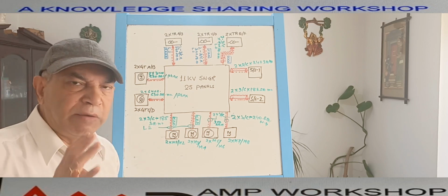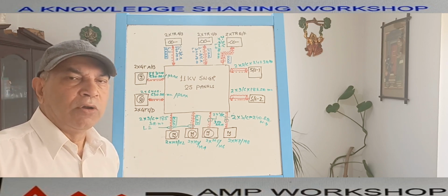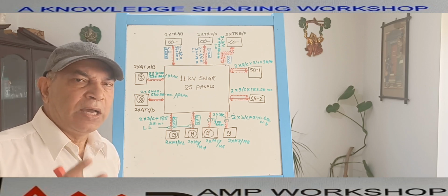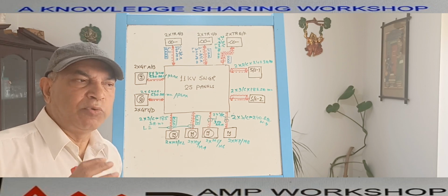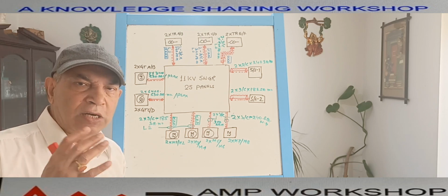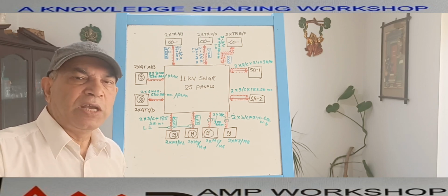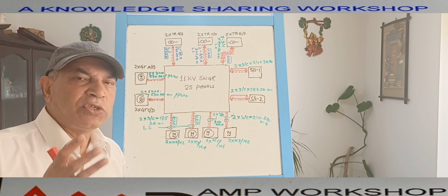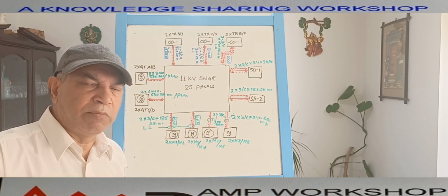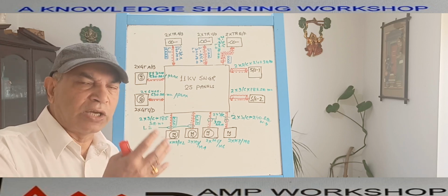Normally all the major power cables connected to the various field equipment are represented by the cable block diagram. The cable block diagram is a pictorial representation of the various field cables which are connected to the various field loads or power equipment, as well as to the generators or the grid.